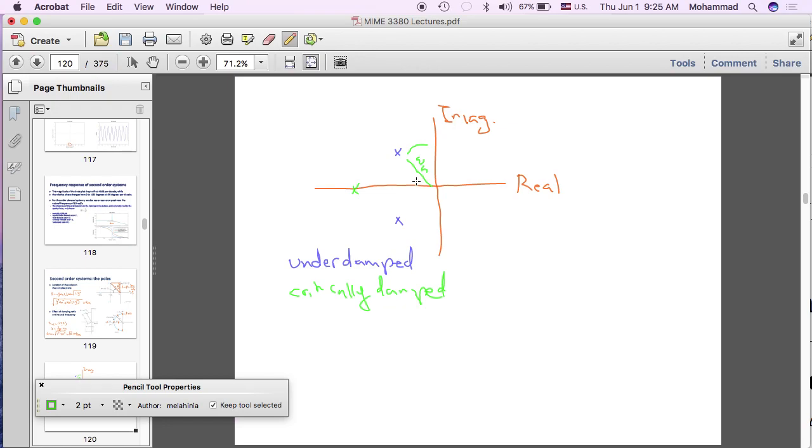So you can see for the green, because the angle is pi over 2, sine of it has to be equal to 1. So this is definitely a critically damped system. But that could throw you off a little bit, because for an overdamped system, the poles are also on the real axis, but the difference is that they're distinct. They're two poles as opposed to on top of each other. So what I just said is, if I give you a third case where you had two poles, that's a terrible choice of color.